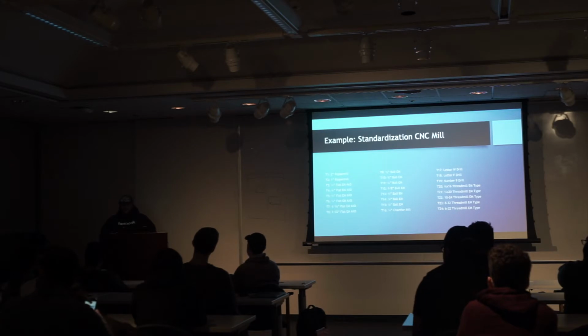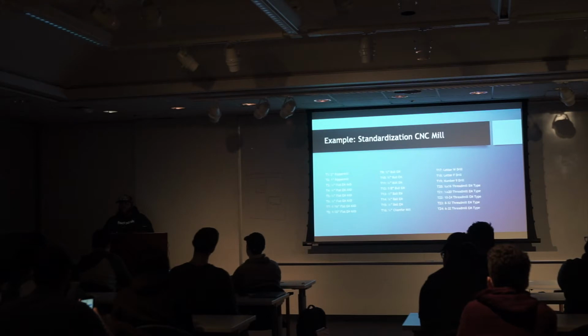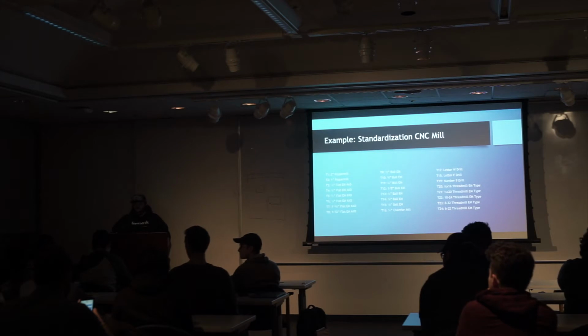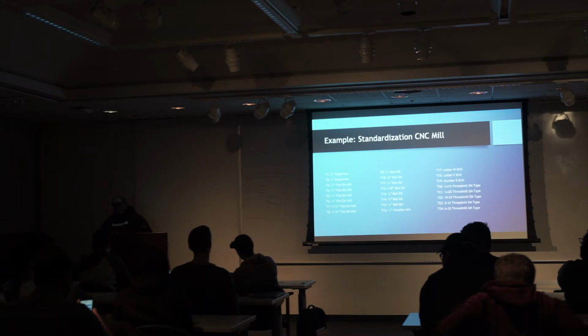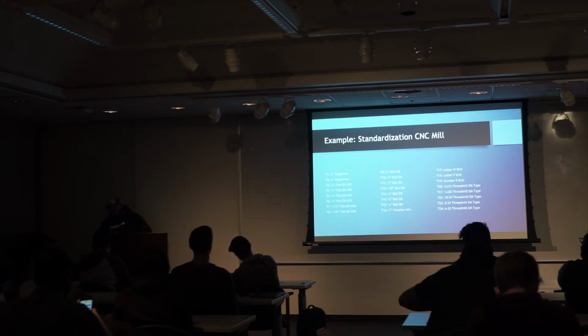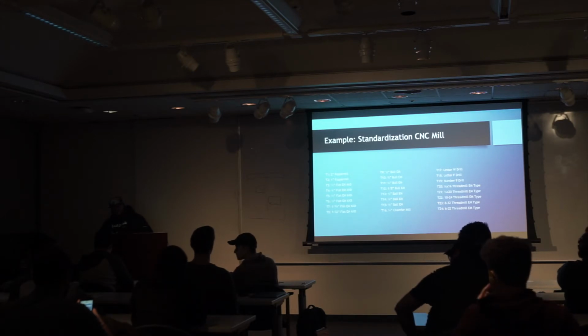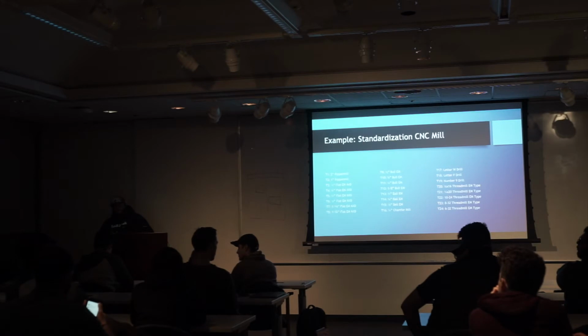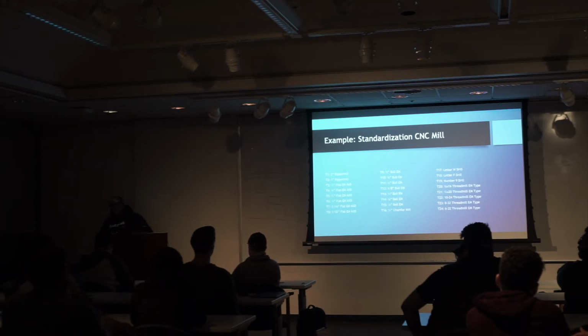So this just goes to GD&T: establish your datums where they matter, on faces that matter, and then dimension things from the datums that you need to dimension them from. It depends on the machine you're using too. If you're dimensioning something to be made on a lathe, you would dimension it completely differently than on a manual mill, or on a plastic mill, and so on. That's why Aaron's job is to check that stuff and make sure it's drawn the right way. But even across all of the machines, GD&T standardizes where all of those dimensions are from and how they should be formed.